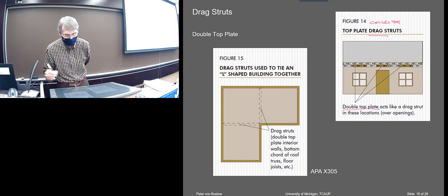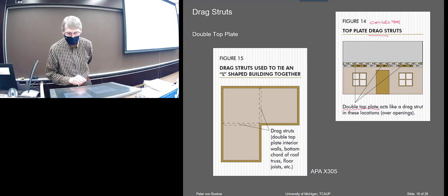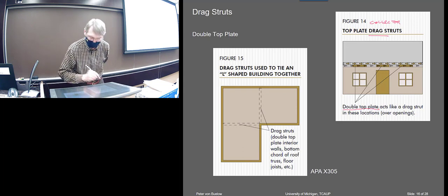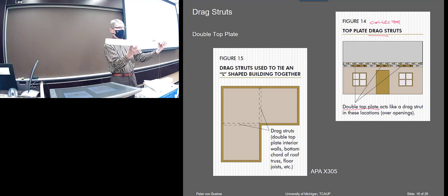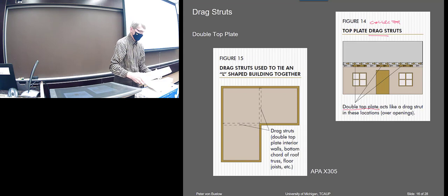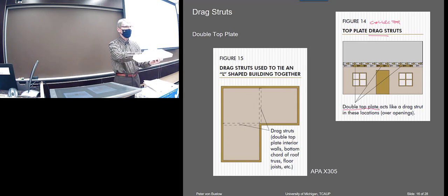All right, this is why it has to be doubled. Well, part of why, we talked about this before too. If it's acting in tension and they're only 8 feet long, they come together somewhere, and they're not going to have a joint there. I think you can get straps that would do that, but you end up making them doubled anyway for the flexural strength between the joists, as a rafter would connect them. So they end up being put on like that.